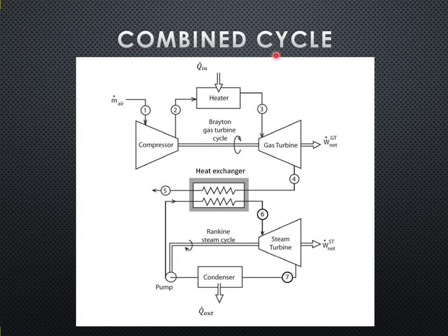This is the combined cycle, the Brayton cycle and the Rankine cycle. So, how do the cycles work when they are combined? Well, first of all, when the compressor starts rotating, atmospheric air moves through the compressor and the volume of the air decreases, but the temperature and the pressure increase, and this process is adiabatic and isentropic.